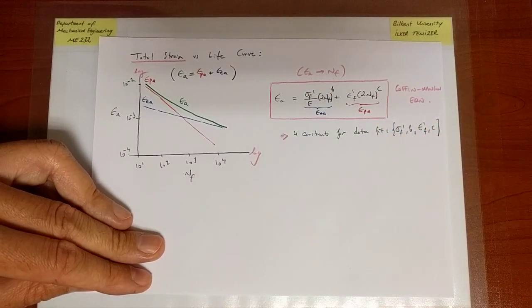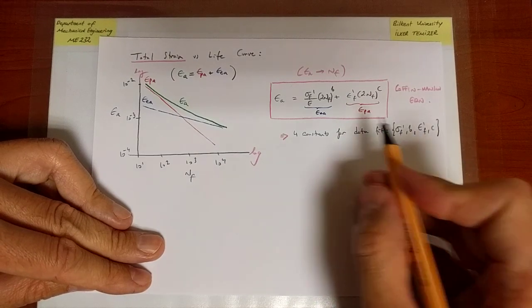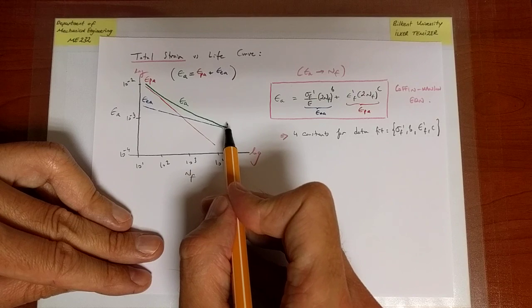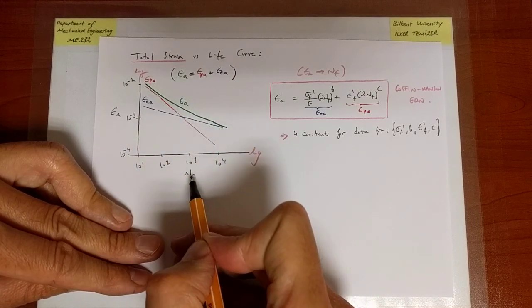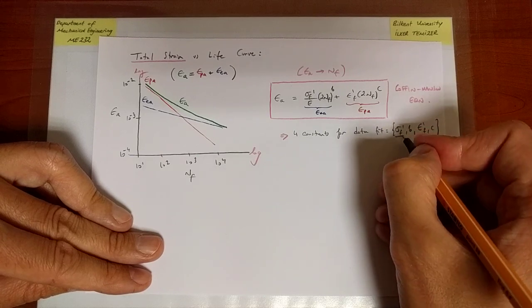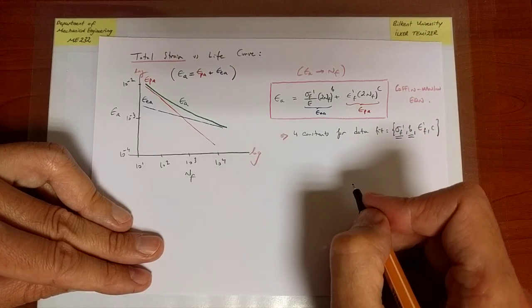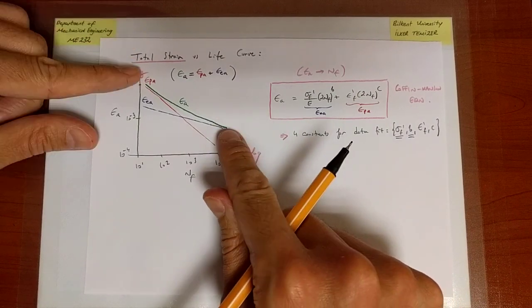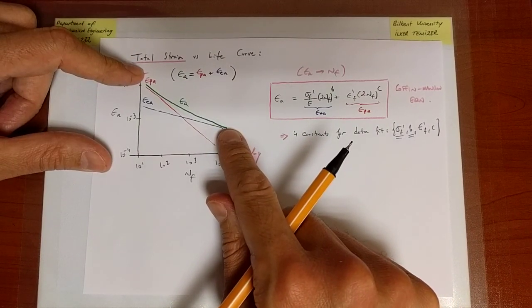And again I highlight, because these 4 constants, for a given strain amplitude, relate the green line to the number of cycles to failure and are used to do that fit. These are constants that I need to determine newly for this range of cycles, which is, in this case, predominantly low cycles.